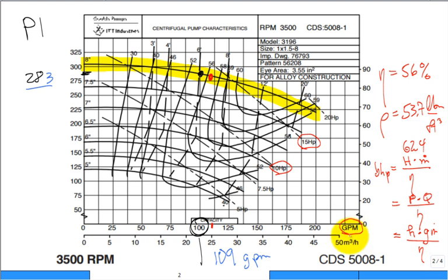Yeah. But you really need to do, for the mass flow rate, this is probably the most convenient right here. Put a Q right here for the volumetric flow rate. Put a rho right there for the mass density of the fluid. Now that gives me the mass flow rate. Multiply by capital H, but luckily the numeric value of lowercase h in foot is exactly the same as capital H in foot pound force per pound mass. True? Numerically, so that's easy.